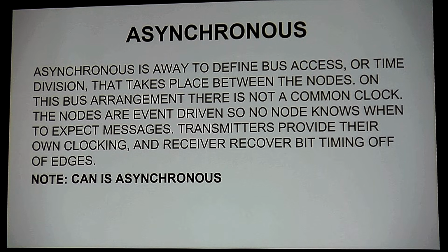In clock synchronization, when I'm clocking off of a master clock, everyone's on the same clock, and everyone's expected to have a message time where I send it. I send this message at this time, this one, this one, this one. So that's sort of how that's going to go, and I'm going to send information in known quantities in known time. Asynchronous is event-driven. That means that I'm not going to send a message till I need to send one. I'm not going to ask for data until I need it. That means I could be sitting idle, and all of a sudden, I need something, so I'm going to come up on the bus, and we're going to try to have a conversation so I can get my data, or you're going to send me the data. I need to ask you for a request. This is going to be event-driven.